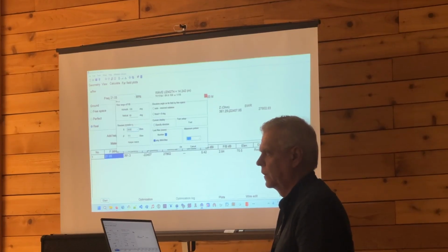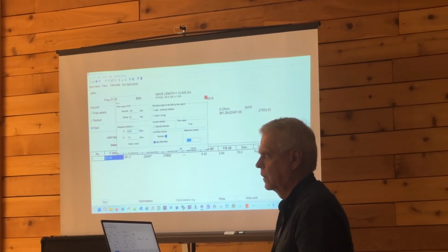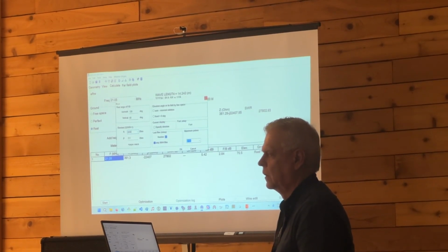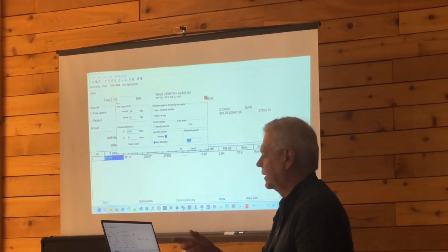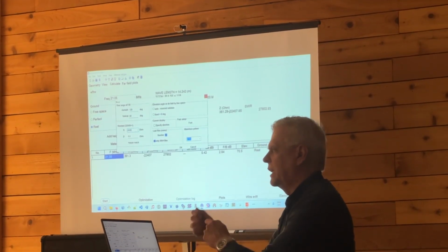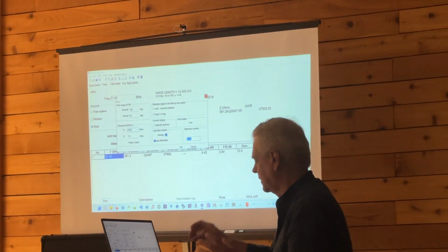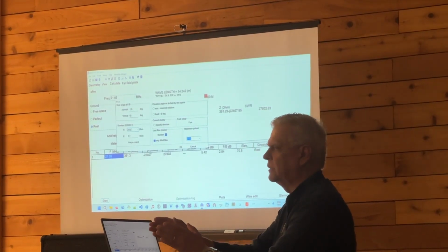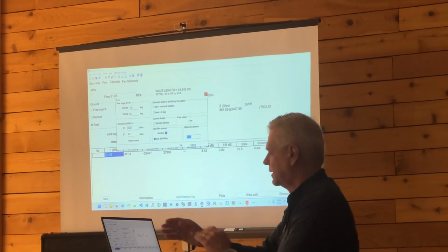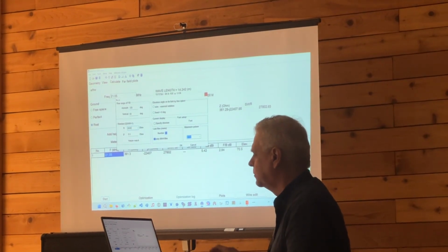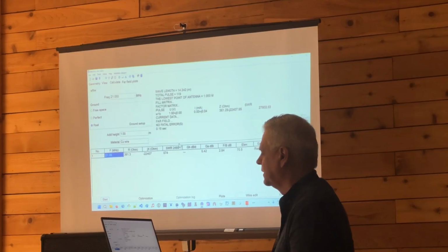Yes, and it implies there is a transformation required to get down to 50. Yeah, that's exactly right. The other way to do it is to actually add a load at the beginning, but I gave up on that. So this seems okay. My 49-to-1 is going to get me down to 50 ohms. So just do the modeling, assuming you're shooting for 2450.